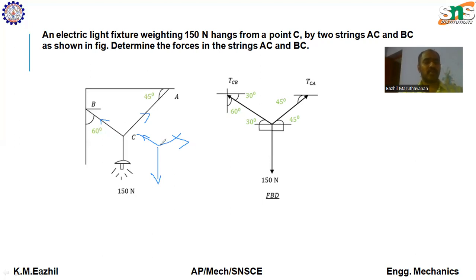Now we have to think of how we are going to solve this problem. Three forces are acting from a concurrent point in three different directions. Can anyone say what law we can apply over here to solve the problem? Yeah, you are right. It's Lami's theorem. We can apply Lami's theorem to solve this problem. For Lami's theorem, you have to find the angles between the forces. You have to find these three forces.